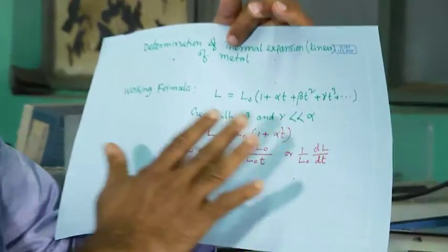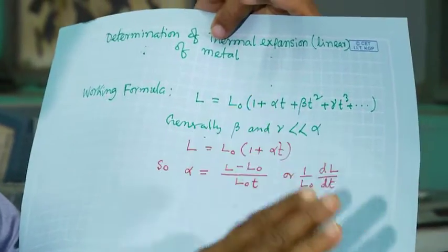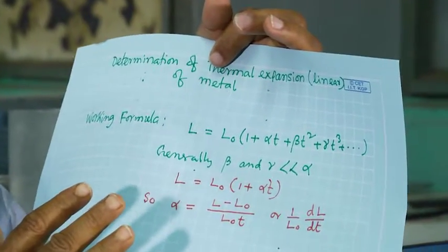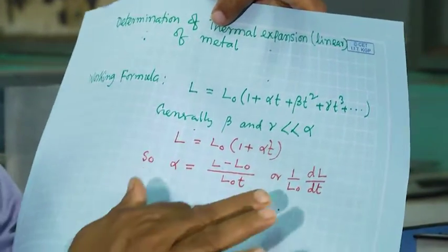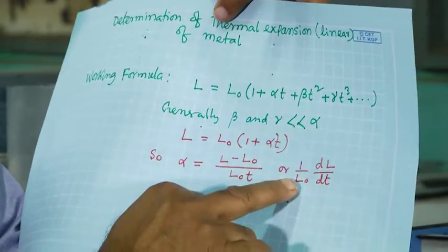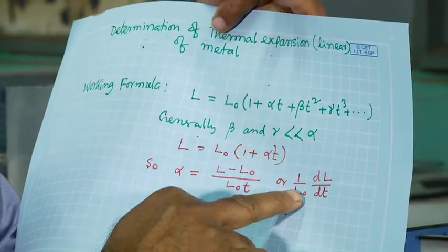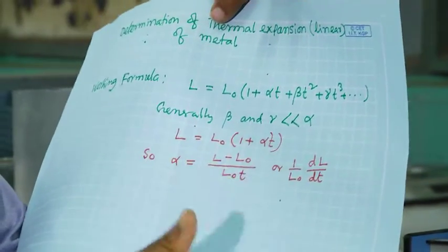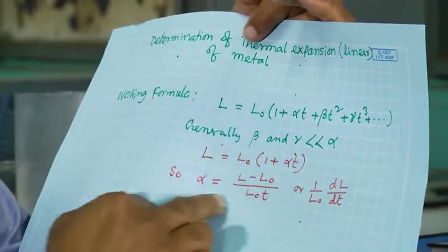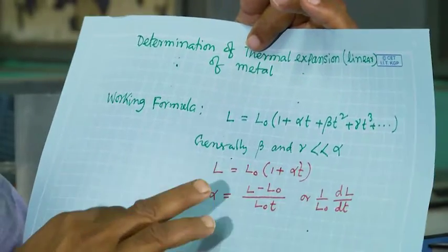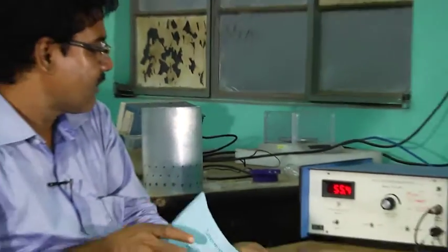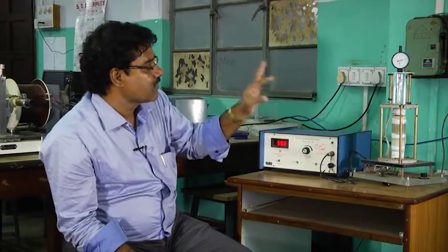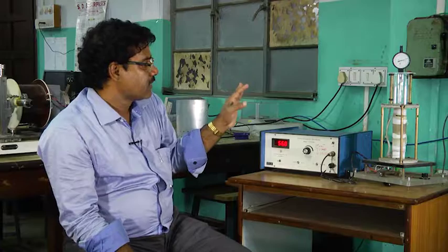Here actually our measurement L0 is given. In our case it is I think 5 centimeter, this metal rod. Okay. And now del L by del T we will find out from the graph, and then easily you will find out this alpha. So, now you see the reading is increasing, and every time you have to note it down. So, the experiment is very simple here.